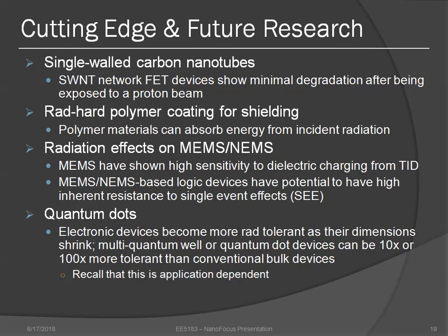So there's actually a lot of cool research going on in this area. I wanted to highlight 4 examples here. This first one, there's a group out of Sogang University in South Korea where they're doing some experiments where they fabricated carbon nanotube network FETs using single-walled carbon nanotubes by an arc discharge process, and that were purified to about 95% by thermal oxidation and chemical treatment.